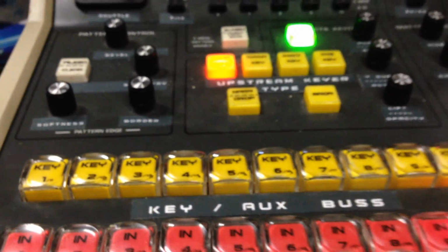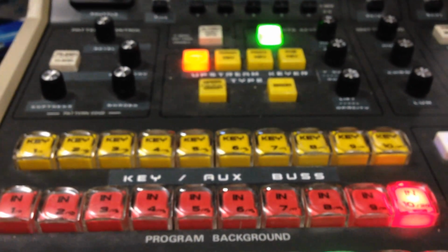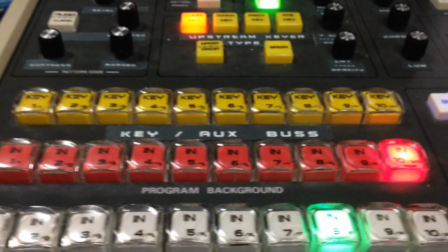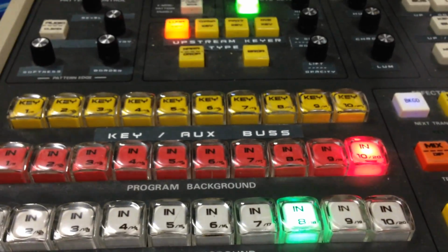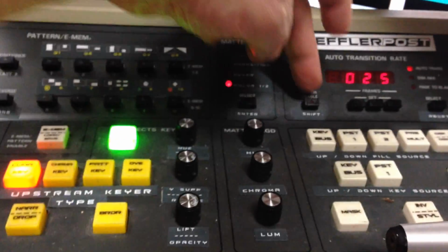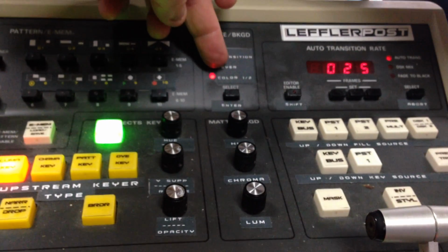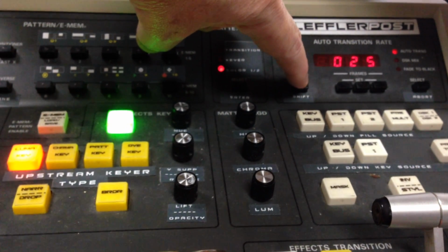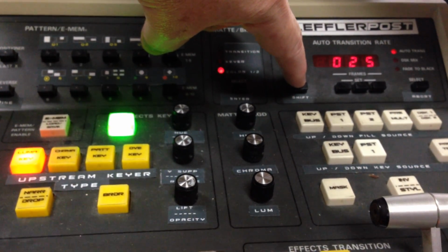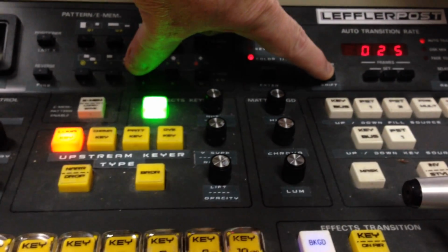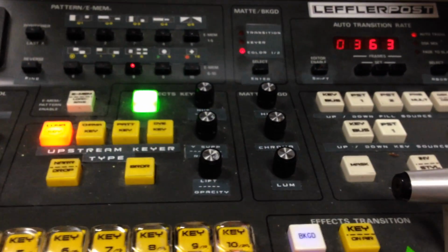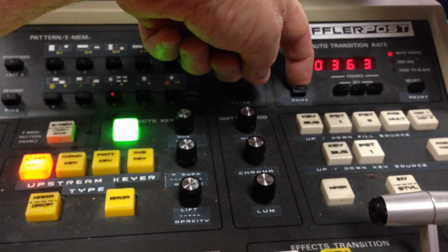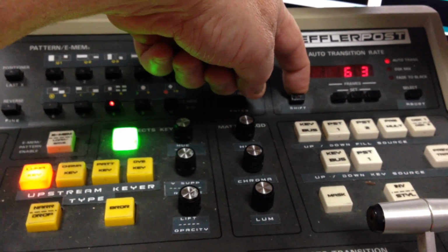A little later on I will be including the ability to save and recall setups for the Videohub key bus buttons. So the way we get into it is, as we did before, using the shift button and pattern 8 while we're in color 1-2 mode. We do what we normally do when going into controlling the Videohubs: shift pattern 8 and then take your fingers off the button. If you hold your finger down on the shift, you go into the IP config setup, which we don't want to do. We did that in video number 1.